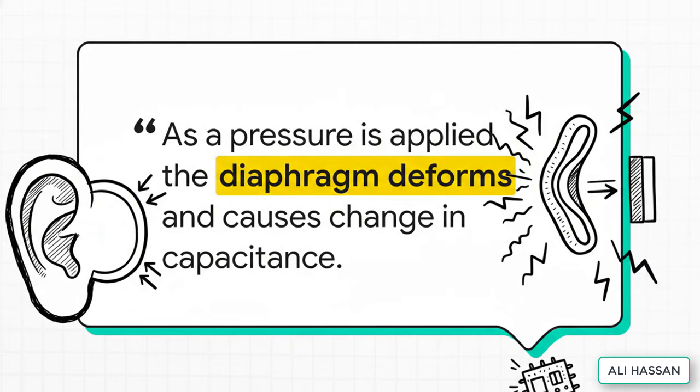The real magic, though, happens in that sensor. At its center is this super thin, flexible membrane called a diaphragm. The best way to think of it is like a tiny, super sensitive eardrum. When pressure from a fluid or gas pushes on it, it flexes just a tiny, tiny bit. And the electronics are so precise, they can measure that microscopic change and turn it into an exact pressure reading.